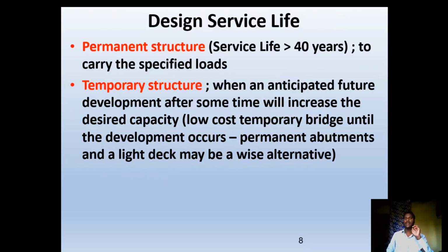Then design service life, the purpose behind construction of the bridge. In that, the first one is a permanent structure or permanent bridge, with service life more than 40 years to carry the specific load. The second one is a temporary structure, when an anticipated future development after some time will increase the decreased capacity, a low cost temporary bridge until the development occurs. Permanent abutment and a light deck may be a wise alternative.